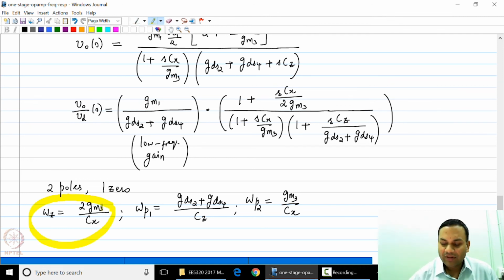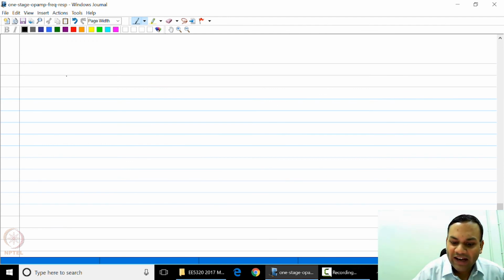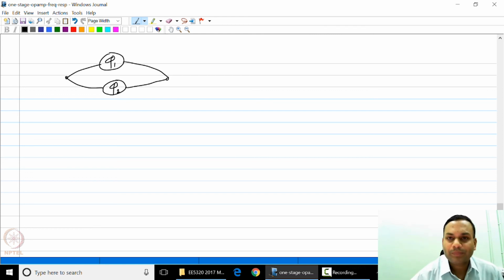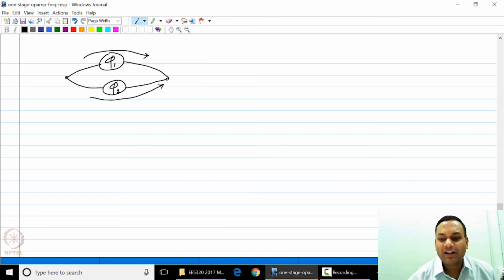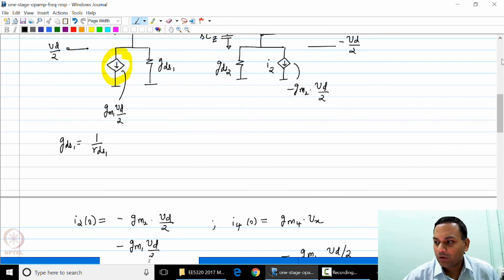and first of all you need to ask yourself why you see a 0. Normally you will find that you see a 0 when you look at the transfer function between two paths. If you see a relative phase shift, especially a frequency dependent phase shift between the two paths, you will normally see a 0. So that through the two paths the signal adds destructively at a particular frequency. Do we have these two paths in the system? It turns out that we do.